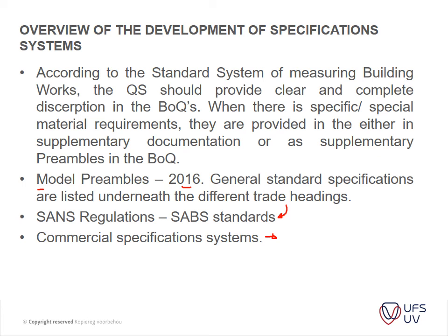So one would incorporate those standard specifications in your tender document. So it's just a commercial specific specification. Or another example would be a specification on paintwork. Dulux have their own application specifications, how it should be applied. The moisture content of the walls should be a certain percentage, and so that specification is then incorporated in your tender document.